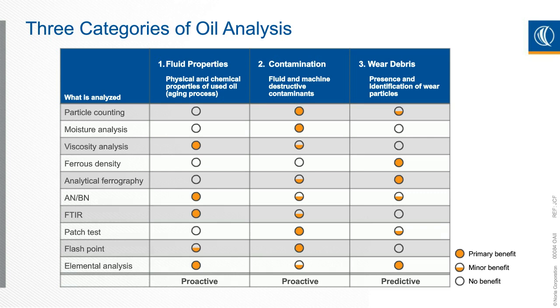If a machine is going to fail, the lubricant will most likely find out first. This is exceptionally critical to understand. Many technologies intend to predict when a machine is going to fail by looking at very specific events occurring. That means the machine is already in early signs of failure. Oil analysis can do this as well, but is also able to observe a whole lot more than that, not just the wear debris indicating that wear has already occurred, but it's looking for events that may say that a failure will potentially happen in the near future.